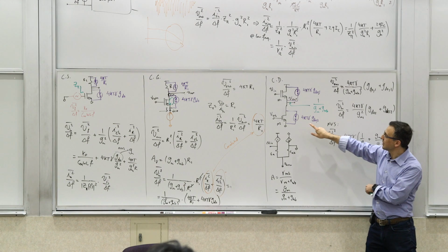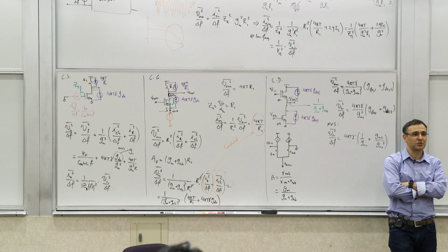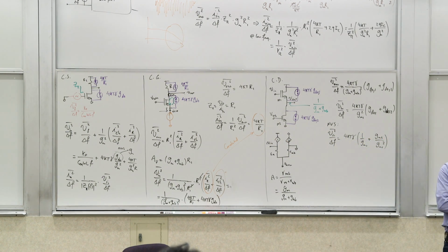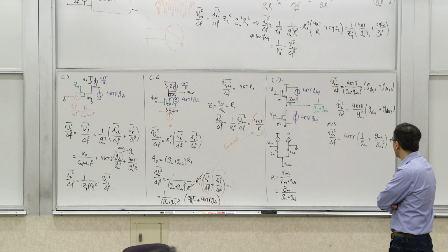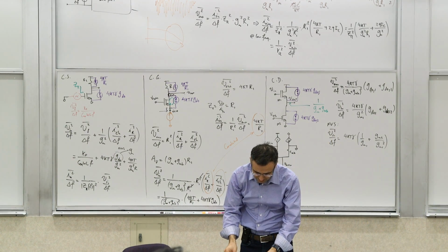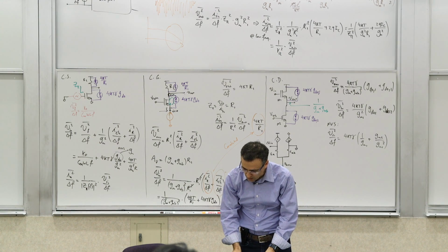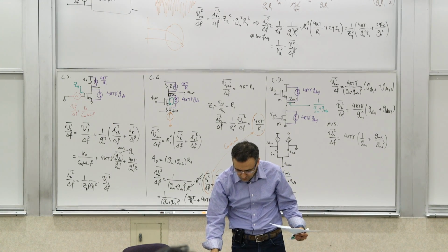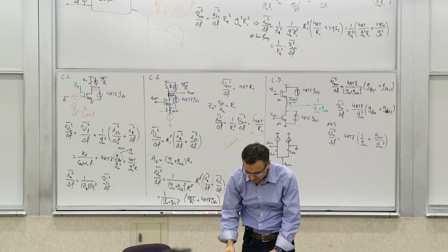So you don't want the transconductance of M2 to be large. You want actually the transconductance of M2 to be small from a noise perspective, but you want the transconductance of M1 to be large and M2 not to be large, if that's the only thing you're trying to achieve, minimizing the input referred noise of this source follower.